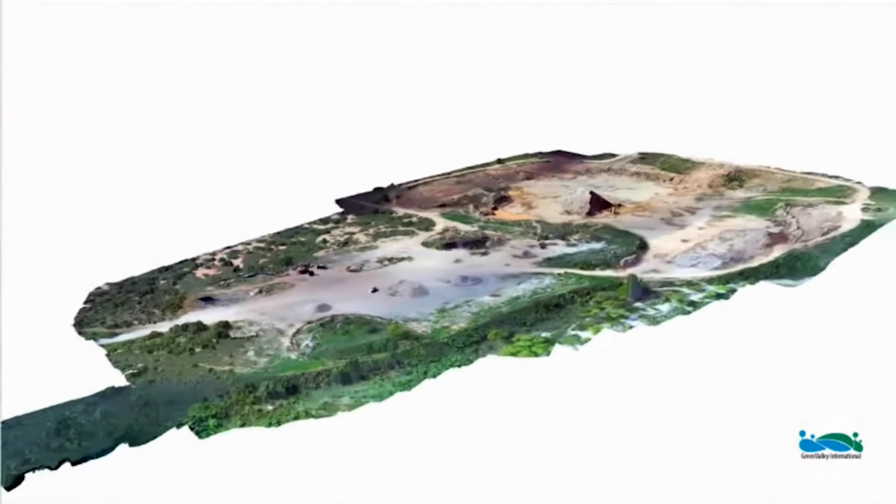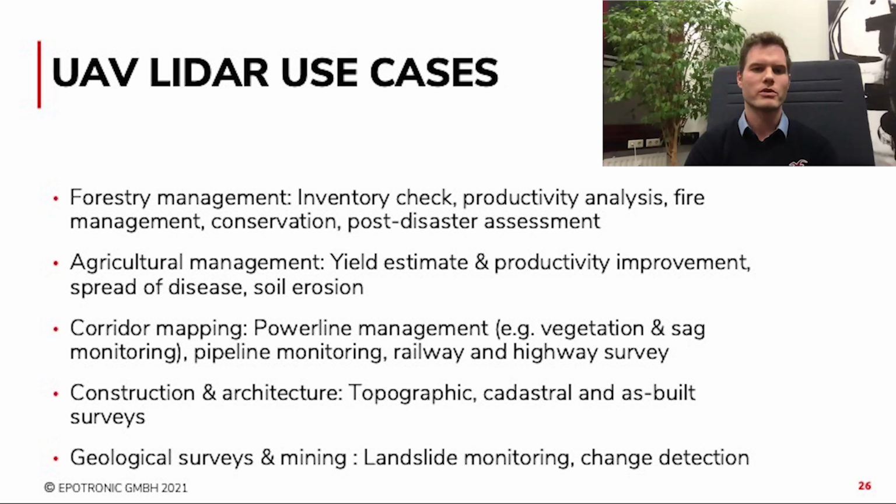And then geological surveys and mining comes a bit similar to this soil erosion topic, with landslide monitoring. Also change detection, volume measurements. Those are the use cases for LiDAR. Maybe very important also to mention that LiDAR is not an exclusive technology. We are comparing here LiDAR with photogrammetry, and in the next slide we're going to show you also a direct comparison, so you could get the impression that we are saying the one or the other is better or less good, but maybe even in the future it's going to be a symbiosis of both technologies. I think, as Liam has already said, we have cameras on LiDAR. The technology is getting smaller, so that means now you can also put the LiDAR and the camera together. It can all be put together way better in the back-end algorithms.